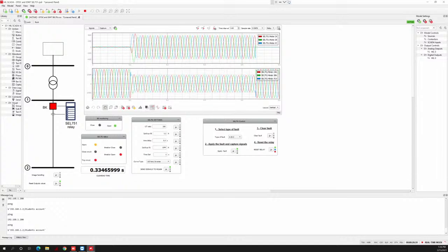Okay, first you need to clear the fault. Okay, you need to do the same in your lab. When we have this situation, the relay stays open. I mean, it is still sending the signal, showing the values, and the circuit breaker will be open, okay, until somebody arrives over there and resets the relay locally. That is one option. Somebody can come here and reset the relay, target reset, or you can do that remotely from the substation using the communication protocol, using the SCADA, using the software from the manufacturer, or in this case, she will use the Python code inside the Typhoon HIL, okay?